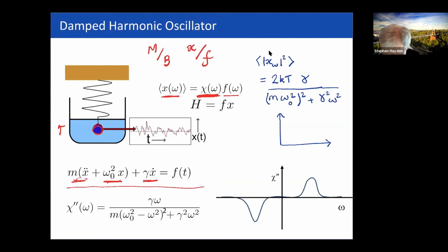So the viscous force, if I just remind you, what we're doing here is dragging a ball through a liquid. So we can use the Stokes force on a sphere. So that would be F is going to be 6 pi times viscosity times the radius of our sphere times the velocity of the sphere.